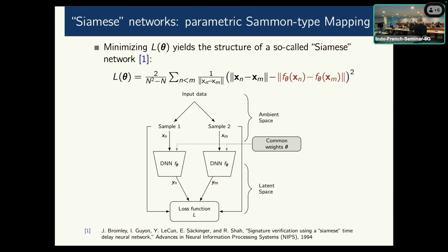Think of the number of antennas at the receiver times the number of antennas at the transmitter times the number of subcarriers. This can be quite high, and we know that when we deal with high dimensional random variables, if you try to compute the Euclidean distance in high dimensional spaces, this distance is dominated by noise. So it's not very accurate.